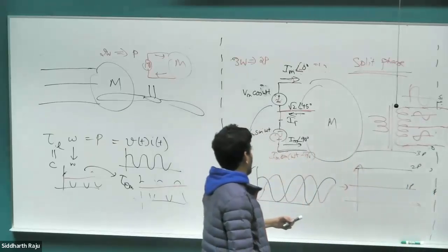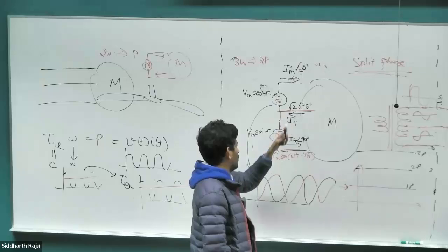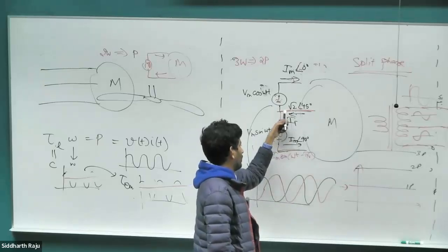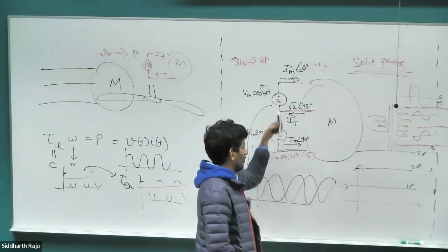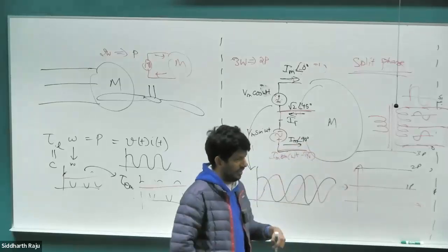One phase, it's worse. And then the other problem with two-phase is that the third wire carries a larger current, not slightly, almost twice the current of the other two wires. While in a three-phase system, all the three wires carry the same current.